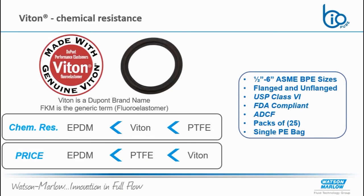You won't typically see a Viton gasket in a pure biopharmaceutical process, okay, but they are out there. It is more expensive than EPDM and PTFE, but it provides better chemical resistance than EPDM and a better seal than PTFE. So while it's not that common, it does round out this portfolio nicely, and you will find customers who may have an interest in Viton.